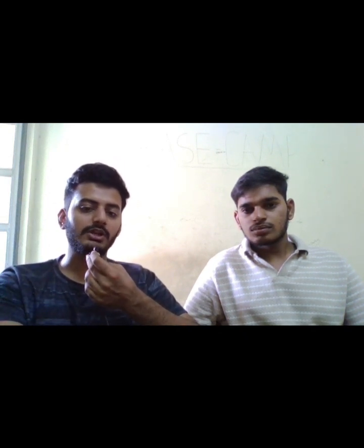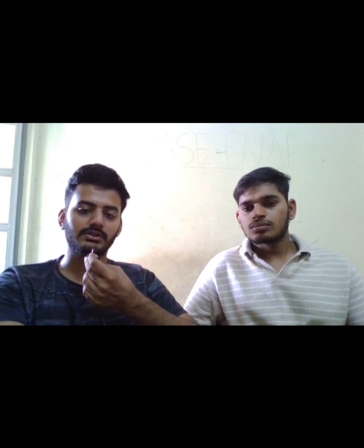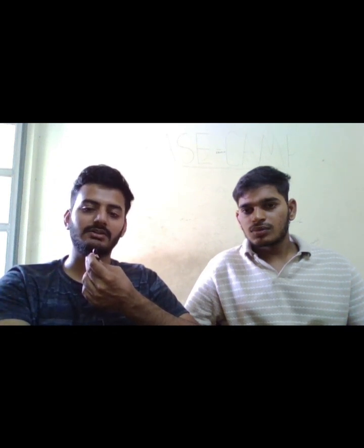Now, coming on to the non-dimensionalized equation, we'll have our bar equation like we discussed earlier. Every term: dv bar by dt bar equals minus del bar phi bar plus 1 over Reynolds number into del bar square into v bar. All these are scaled variables, all dimensionless, and the whole equation is dimensionless. Now coming on to the main part of the dimensional analysis.